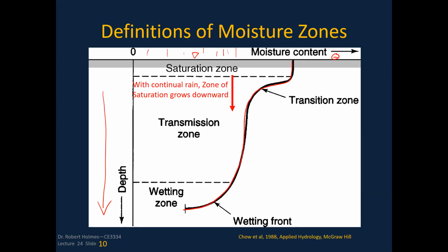You've got the saturated zone up here at the top. And way down here at the bottom, we've got the water table somewhere down here. Between the water table and the ground surface, when it's not raining, that is unsaturated soil, so there are air voids. So it starts raining, we get a lot of precipitation, and you start getting this moisture to change as moisture infiltrates into the soil.